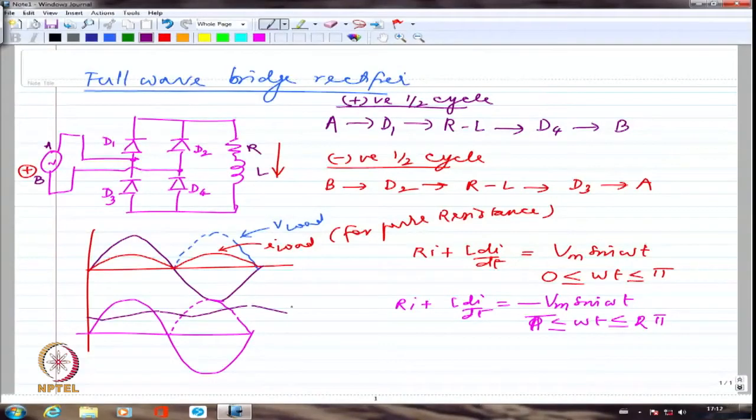You can see that the current will essentially see very minimal oscillations if I have a larger and larger value of inductance. Higher the inductance value, the ripple in the current will decrease because the inductance acts like a filter. Whenever there is a shortfall in the energy, it is going to supply back. So the amount of energy supplied back is going to make the current fall or current rise really minimal. That's what is going to happen.